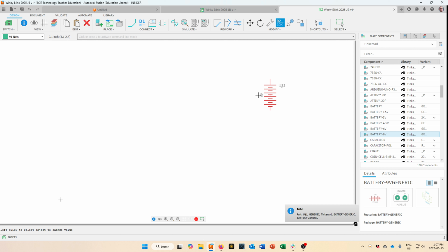And then we should be able to pick that up. I had to hit the escape key to get out of that redefine, and there we go. It says 9V. If you want to get really fussy and bring that in nice and neat, you can zoom in or zoom out with your center mouse wheel. And by holding down the Alt key lets you do fine adjustments on your grid right there. Okay, so we've got a battery in there. It looks pretty good. Nice.